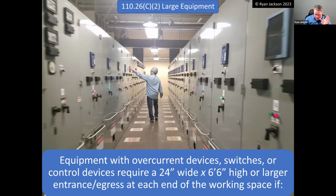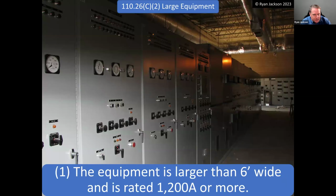Now, again, I want to be very careful here. This does not require a Chapter 10 IBC means of egress from each side, right? If this guy can walk to the end of that picture and, if at the end of this row of switchgear, if he can get past the switchgear by at least 2 feet, he can have a brick wall on his left and his right. That complies. You just have to be able to leave the working space on each end of the equipment if the equipment is bigger than 6 feet wide and is rated 1200 amps or more.